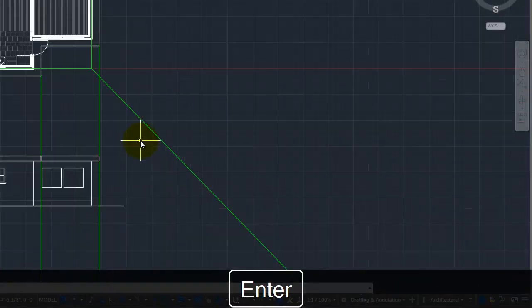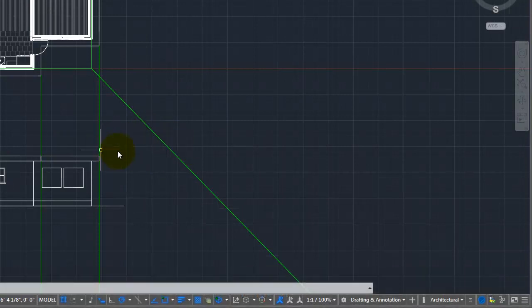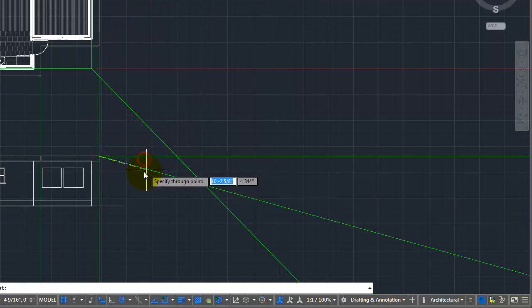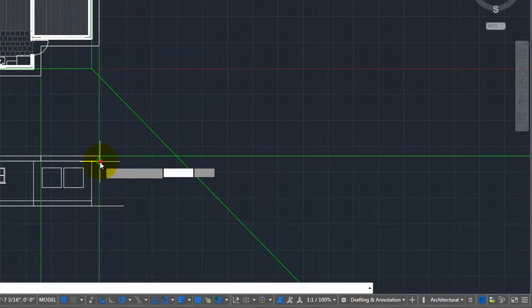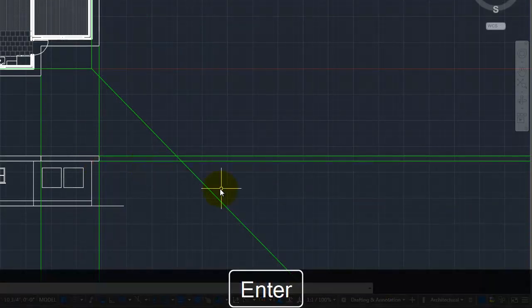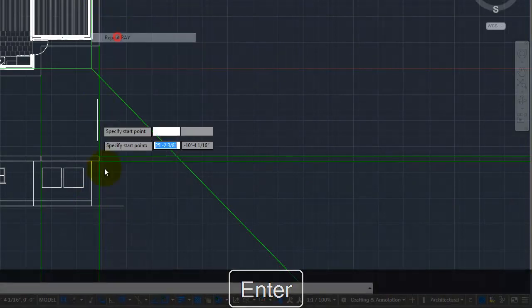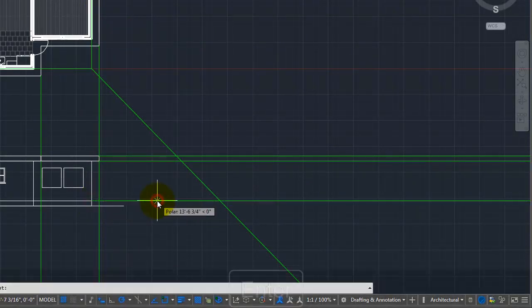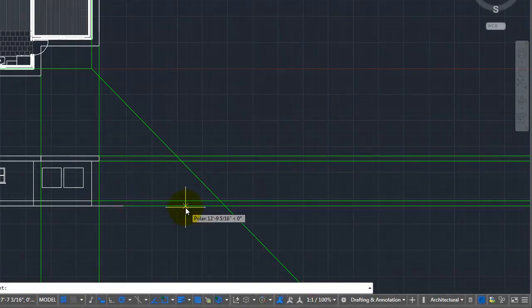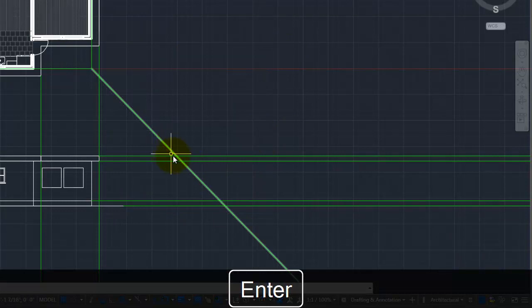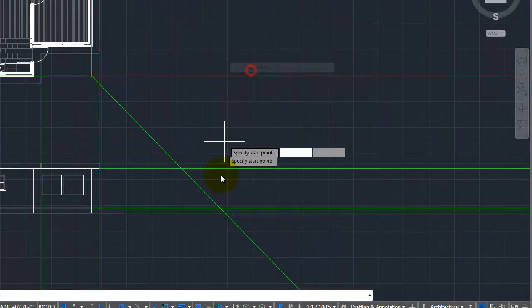There it is. Okay. Now, what happens here is I can actually use my rays to reflect lines up here. So I'm going to repeat the ray command. And if this doesn't make sense, bear with me for a little bit. I hope that it will. I'm going to draw a ray from each of these main points. There. Now I'm going to come to these intersections, and I'm going to repeat the rays going up.